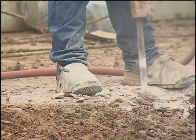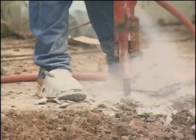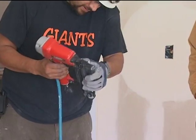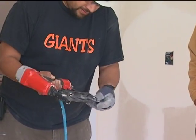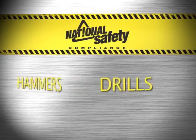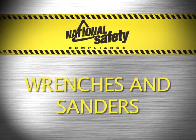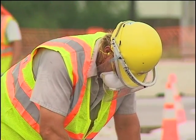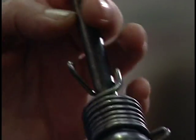Pneumatic tools, or tools that are driven by compressed air, are commonly used on construction sites and in general industry. These tools can be dangerous if used improperly and include chippers, drills, hammers, impact wrenches, and sanders. One of the main hazards is getting hit by one of the tool's attachments or by some kind of fastener the worker is using with the tool.